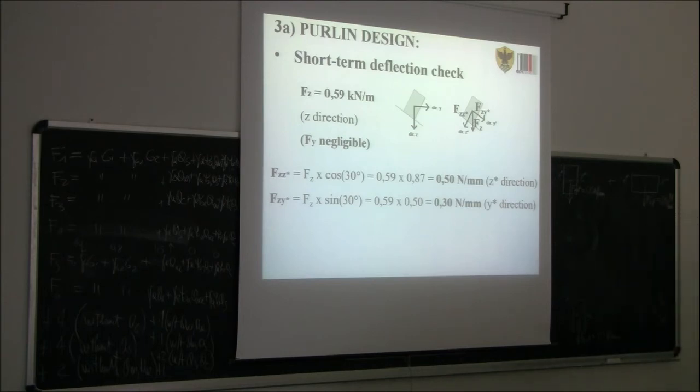So the biaxial bending moment is basically decomposed in the sum of these two simple bending problems here. Okay? So one is bending around the strong axis, and the other one is bending around the weak axis. In this case, we need to calculate the deflection using the formula that we know. So we know the area, we know the length.